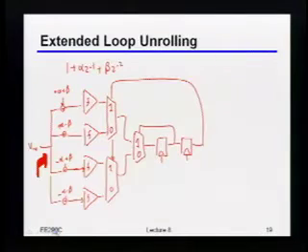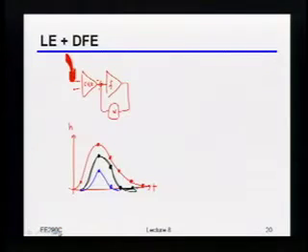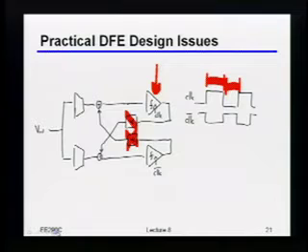So indeed, if you end up doing a two-way interleaved, then you should probably go ahead and do the loop unroll as well. Because if you don't, then it may not really be buying you all that much, unless just generating a clock that fast is really expensive. Does that make more sense now? Kind of. It's still not clear that it's that much of a speed benefit, but maybe.